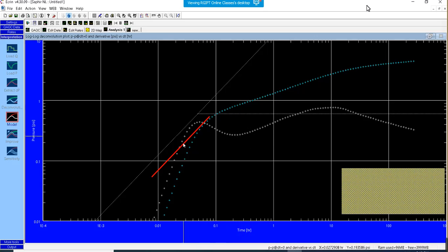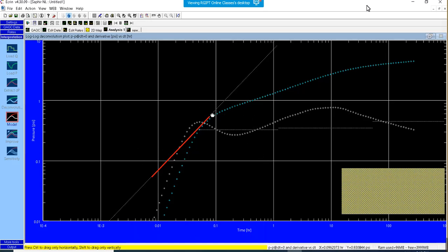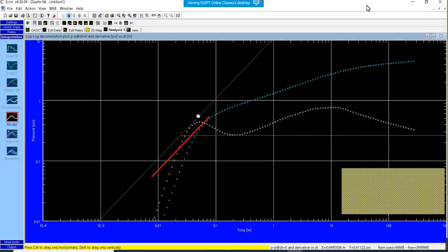And again there is another hint that there is no wellbore storage. So it seems to me that in our ETR I have a fracture, and it has a significant amount of storativity. Therefore, pressure transient will give some stabilization for a smaller time in the fracture zone also. After that, there will be a transition, and then we'll shift to the main reservoir, and it will come later.